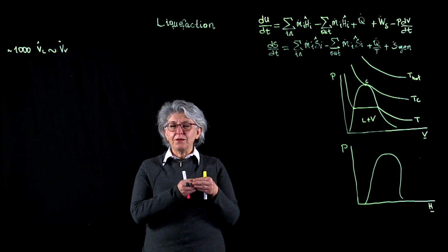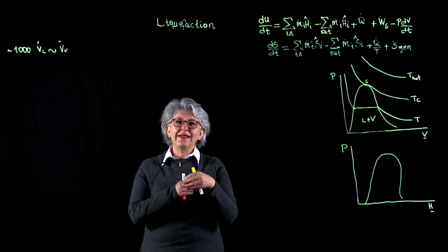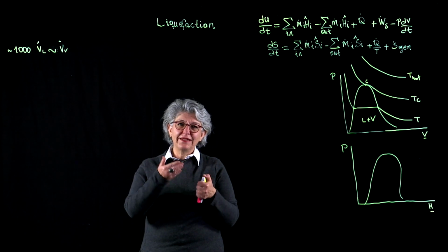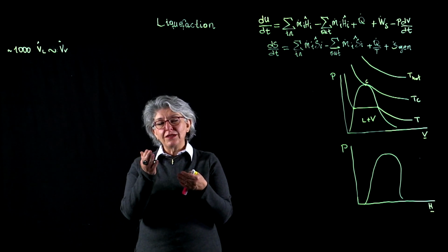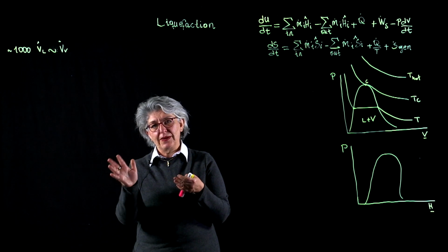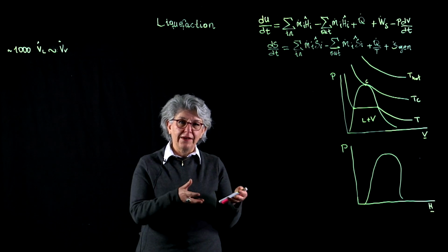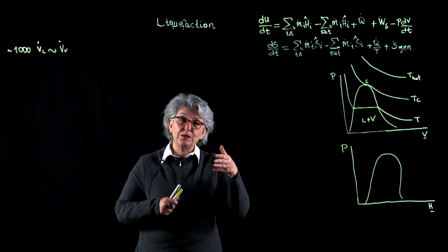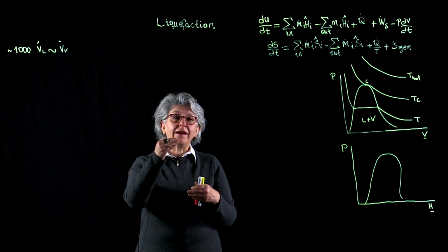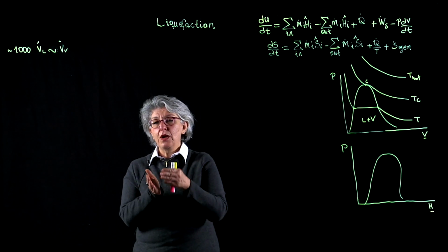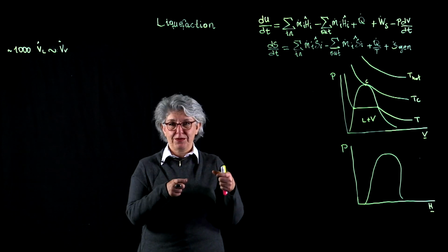The reason for this is that when you do combustion in the absence of nitrogen, the energy that is taken up by nitrogen molecules to heat them up is no longer needed, because nitrogen molecules are not there. As a result, all the energy goes into whatever molecules exist as a combustion product plus whatever process you're doing, and it is possible to achieve very high temperatures. So we transfer combustion energy to a smaller number of molecules. As a result, we obtain higher temperatures.